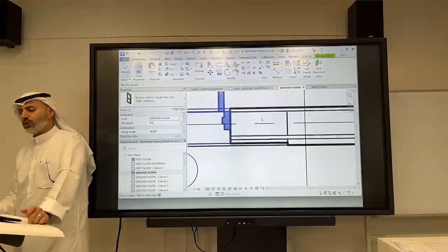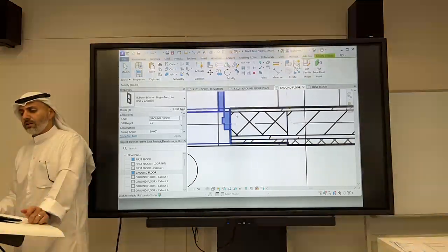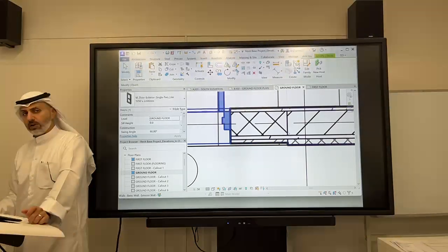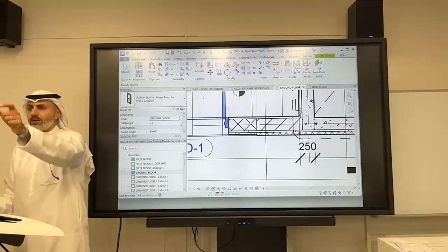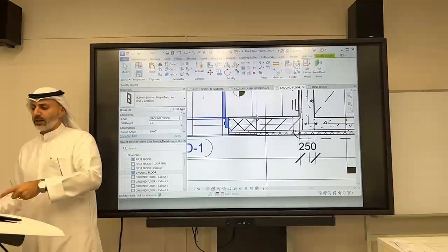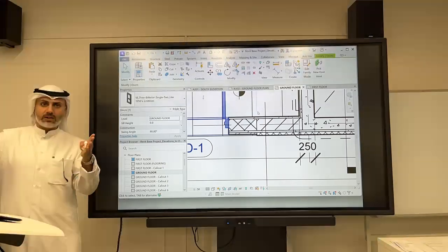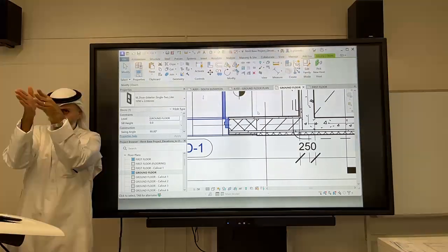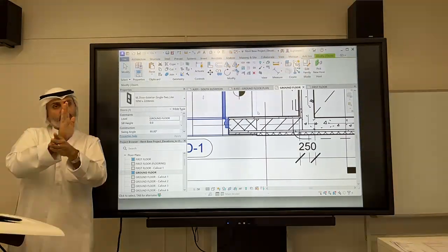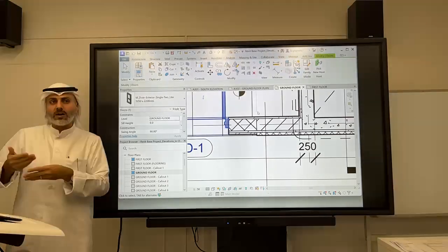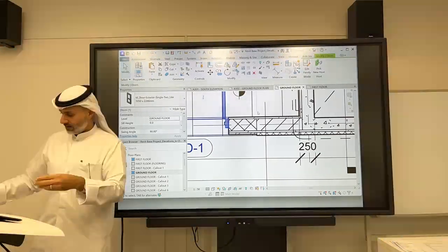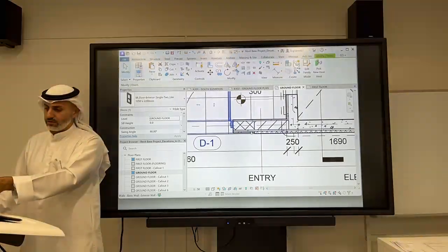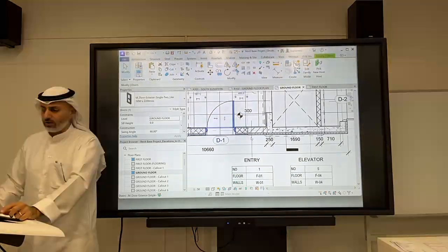Then what am I showing? I'm showing that here there's a brick. This is cross hatch, which is the black brick. Imagine if I push the door here, say only 5 or 10 cm away from the other wall. What I'm saying practically is I'd have to bring a brick and cut it this thin and then put the door next to it, which in construction is not very practical unless you have a really good reason to do it. Avoid it and push the door away a set dimension from the edge.